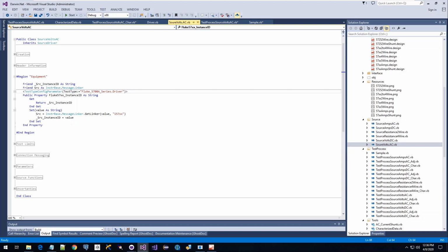Are you talking about that type of simultaneous metrology? Yeah. So you could have the 5700 in the morning characterize itself with the 3458. When that process is done, you can use your 5700 to go calibrate meters, and you could use your 3458 to go out and calibrate function generators or something else. So that's what you would get in simultaneous.